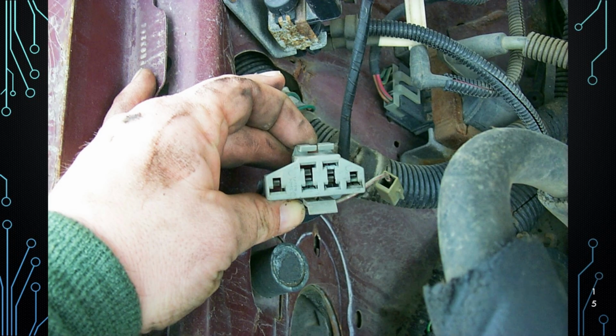That L-shaped connector is from a Ford vehicle. It's part of Ford's EEC4 system used throughout the 1980s and early 1990s. It served as a diagnostic port. Using a scan tool or even a jumper, you could retrieve flash codes. It was key for checking engine faults before OBD2. That is correct. Got that one.